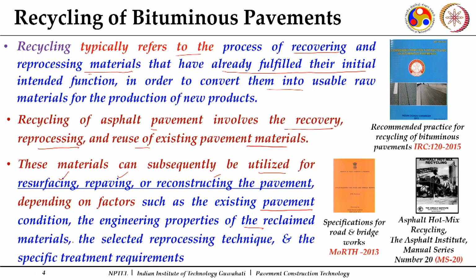The second factor is the engineering properties of the reclaimed materials. So, what reclaimed materials do we have? We have aggregates already coated with aged binder. What are the properties of it? What sizes of aggregates are we able to get? How much coating of binder is there? What is the condition of that aged binder? These properties of the reclaimed material will play a role in what we can do with those materials.